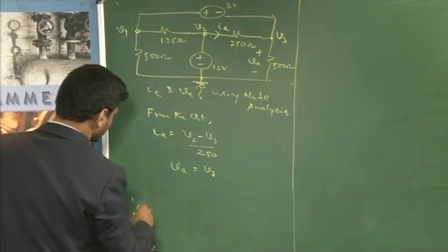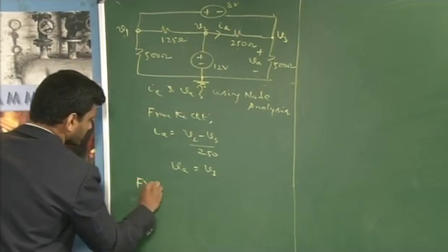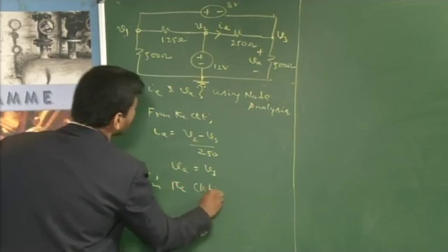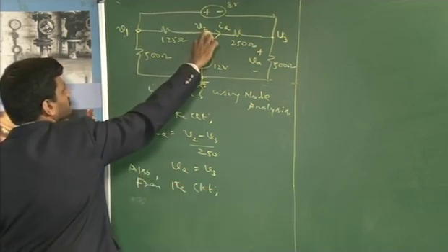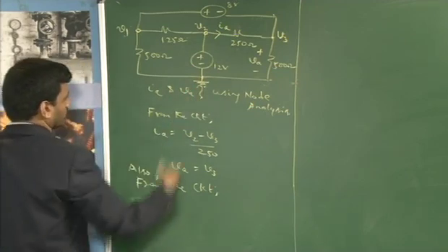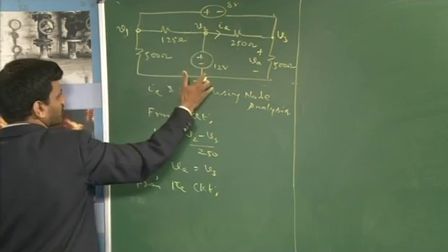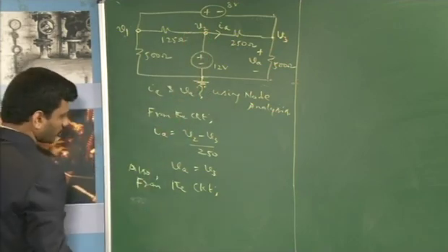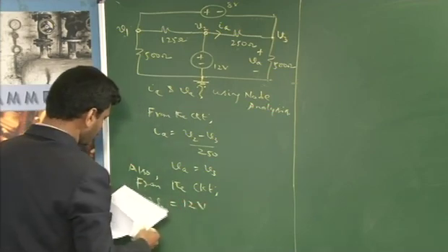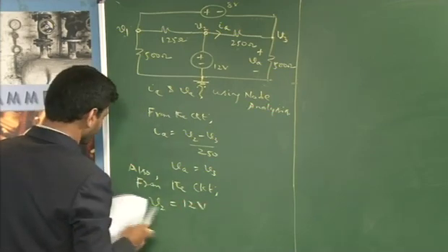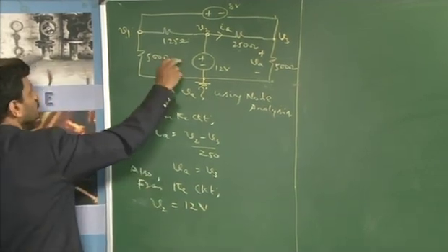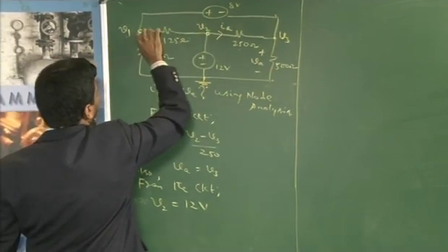Okay. Now, we have to be very good observers, right. So, what we observe here is, from the circuit, V2 is the potential difference between this point and this point with this as reference. And what is 12 volts? 12 volts is the potential difference between this point and this point with this as reference again. So, what we can say, V2 is straight away 12 volts. Okay. Right.